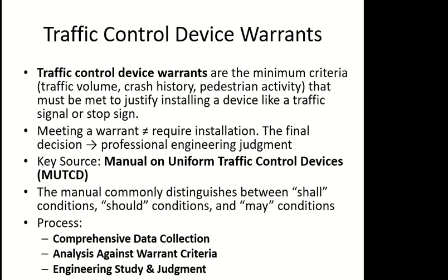And you may do some other studies on the basis of your comparison. So I compared the volume with the warrant. The volume was less than what the warrant is saying. So according to the warrant, the device is not required.